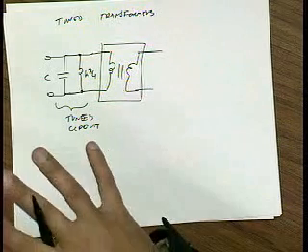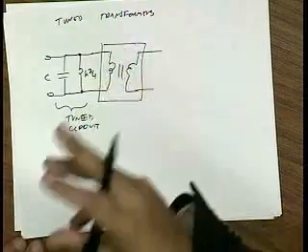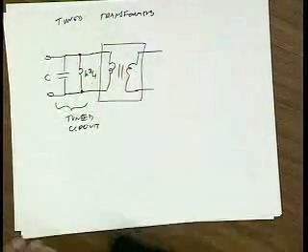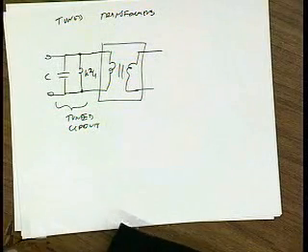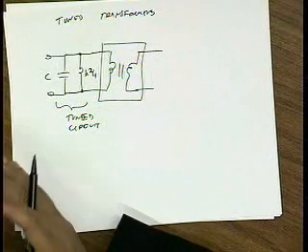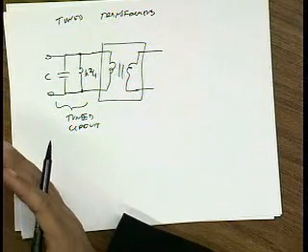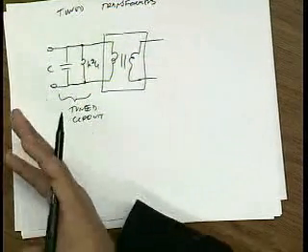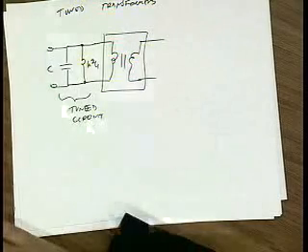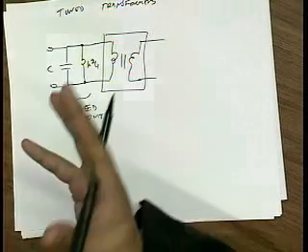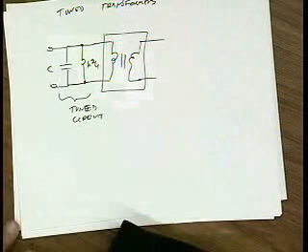I mean, you're limited by how fast you can switch transistors and the actual GM of the transistor. So we know the GM of the transistor starts going like FT over F. So if we get closer and closer to FT, we have less and less GM. Then our ability to switch transistors gets worse and worse because of that huge capacitance on these devices.